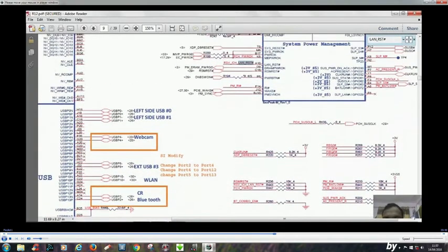This is the LAN reset pin inside the PCH, and here the signal is RSV_ICH_LAN_RST. It is grounded because we are not using the Intel PHY devices. The Intel internal LAN is not used, so you can see this is grounded.